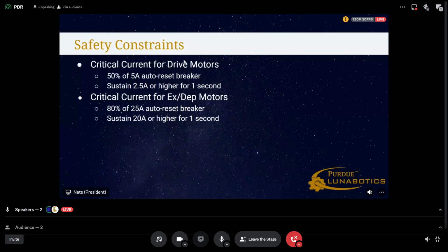Because of that, we were running MPC much slower, at 2 to 5 hertz, since the output of our position was at 10 hertz. That rate limits how fast we can move without hitting a rock. So we would want to bump it up by an order of magnitude, and 10 to 15 hertz is, I think, a good sweet spot for MPC.